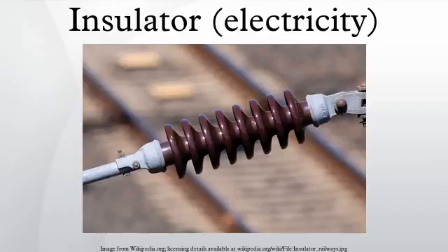Electrical wires may be insulated with polyethylene, cross-linked polyethylene, PVC, Kapton, rubber-like polymers, oil-impregnated paper, Teflon, silicon, or modified ethylene tetrafluoroethylene. Larger power cables may use compressed inorganic powder, depending on the application.